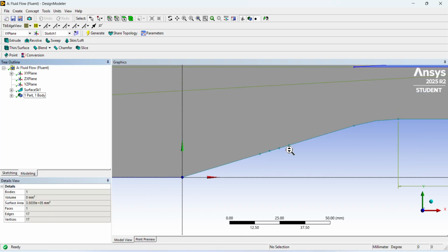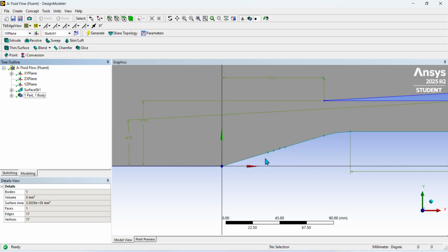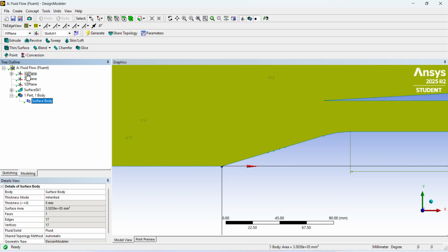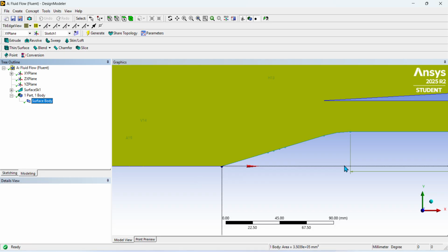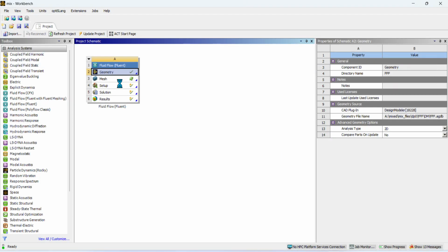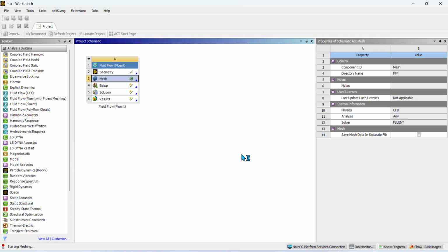Now I have two bleeding holes. Previously I had only one bleeding hole. Same process: again I will go to the mesh window. I will make these two outlets, and I will give the same outflow. I will do the analysis and obtain results similar to the first bleeding process. I will just finish with meshing. The remaining part is the same.